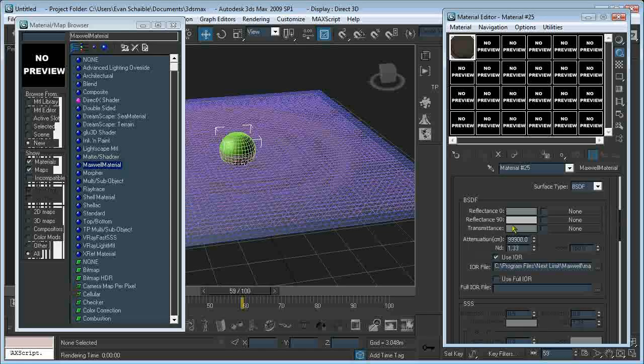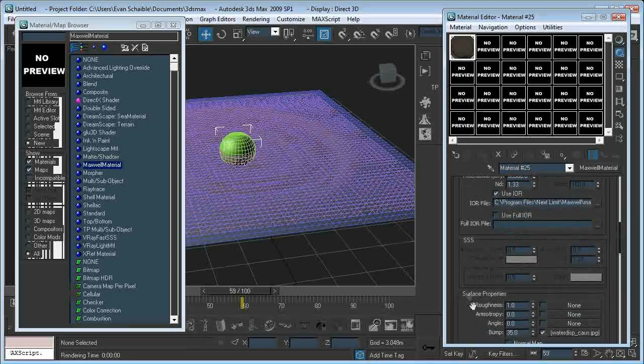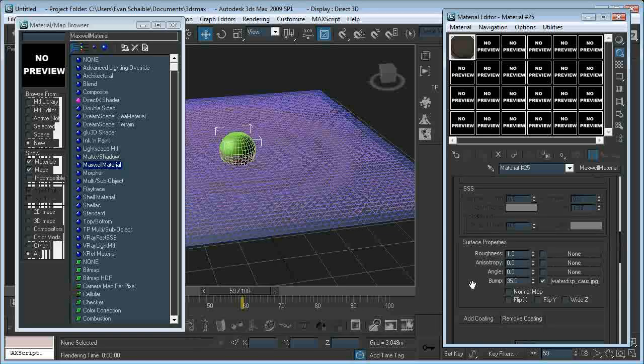As you can see here, I just have really pale aqua type colors. And the biggest thing with water is getting the transparency right, and that's pretty easy in Max with the material editor, especially if you're using Mental Ray, which has the ArcViz water and window materials built right into it, so you can use those and customize them as you need.